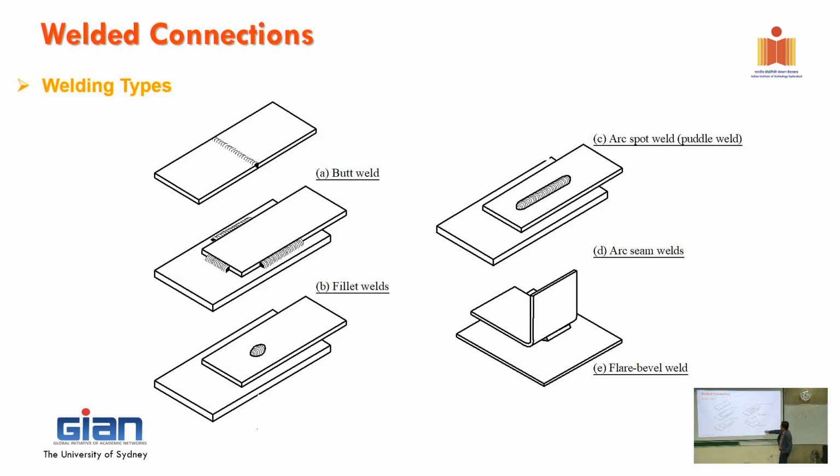So this is different because with thin sheet, the top plate is very thin. So actually we can put the weld and melt it through the first plate, and it melts down to the second plate. So you actually can do that. So this is what we call a spot weld, and instead of one dot you can drag it, and then you have a longer spot weld.